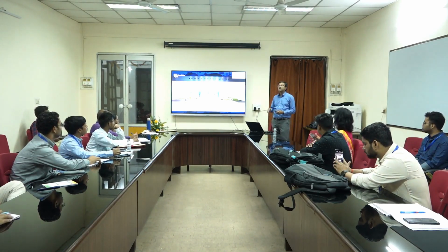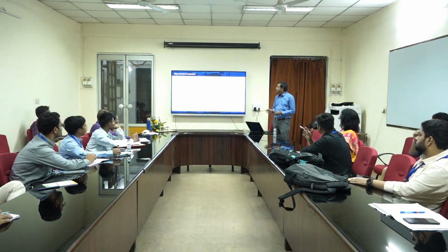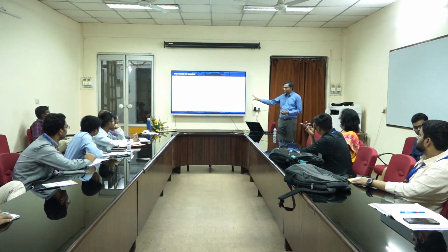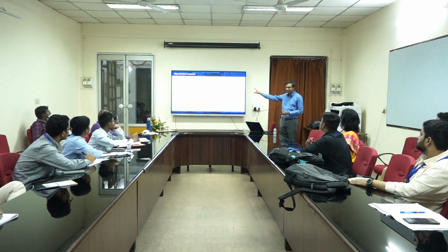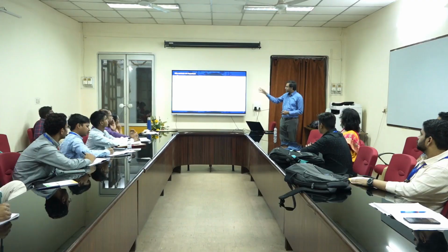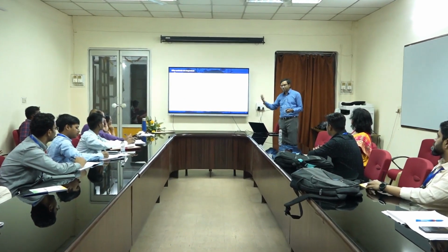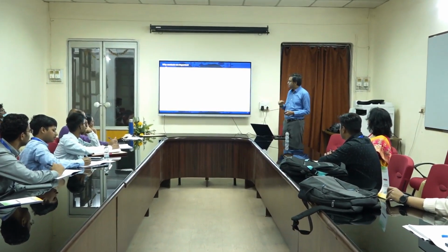Okay. So now let us see in the context of transistors that we were talking about in the first lecture, why are contacts important? So we go back to this transistor structure, very basic, source and drain, and the source and drain, as I told you, are the metals. That is where you are connecting the 2D material to the external world, and then you apply voltage in order to enable current flow through this material.